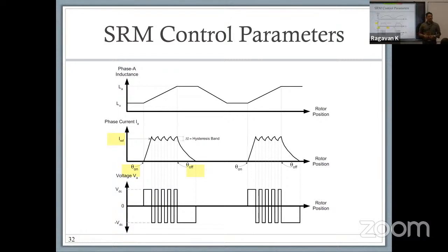The difference, of course, is that your system does not have a fixed switching frequency, because you are essentially varying it as need be. The benefit is that you are able to control the current more effectively. So even if you end up having a 0 duty cycle, or a 100% duty cycle, which normally you don't do, this allows you to let the current go as high as it needs for as long as it needs. So you do that and you apply current. Keep in mind, this tail that we got because of the inductive effect, you have to take into consideration.